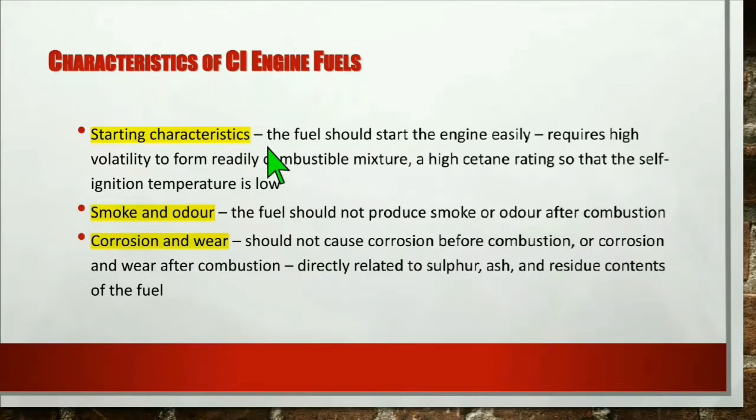Starting characteristics. The fuel should start the engine easily, which requires high volatility to form readily combustible mixture, and a high Cetane rating so that the self-ignition temperature is low. Smoke and odor. The fuel should not produce smoke or odor after combustion. Corrosion and wear. Should not cause corrosion before combustion or corrosion and wear after combustion, directly related to sulfur, ash and residue contents of the fuel.